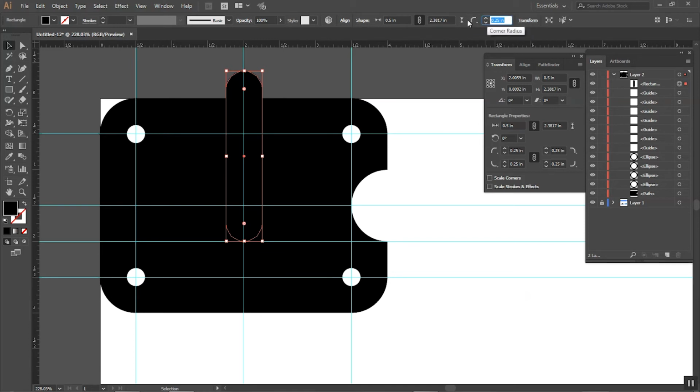And that's updated, that's mentioned here as well. So that's a corner type. You can choose different shapes. We actually just want the regular radial fillet. So that makes that an arc running the whole way around there, 0.25 radius, which makes sense for a 0.5 wide element.